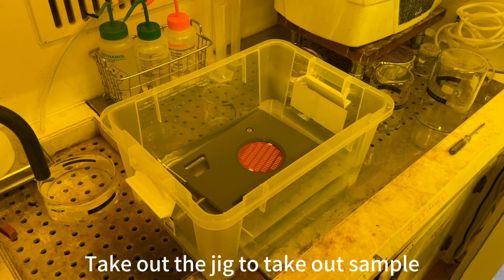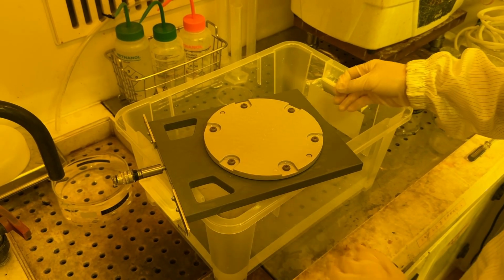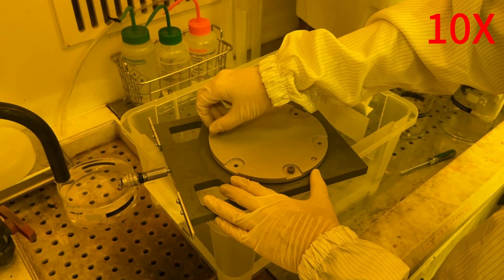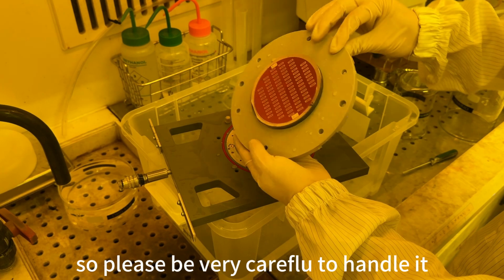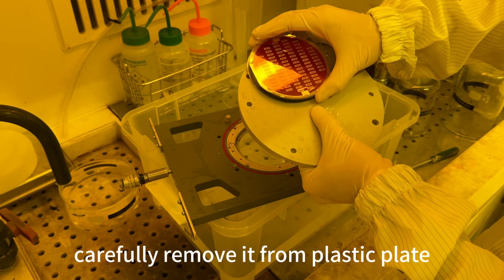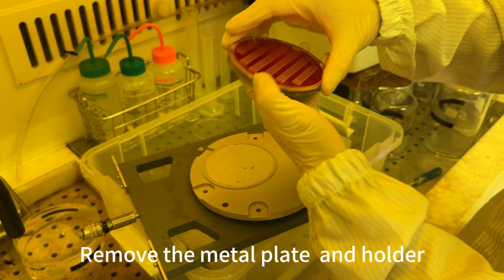Take out the jig to take out sample. Loosen the bolts. Take out the plastic plate. The sample will be fixed on the plastic plate, so please be very careful to handle it. Carefully remove it from plastic plate. Remove the metal plate and holder.